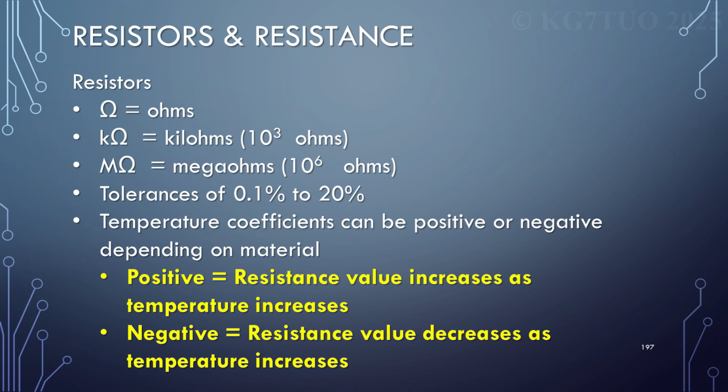As an example of why we should care, the older transceivers that had tubes and discrete components, resistors, capacitors, as they warmed up, they would drift in frequency. So you'd be tuned into your net frequency, and pretty soon you were off frequency because it would be warming up. So you would turn the radio on and then go have lunch and come back, and then it's probably pretty stable. You'd take it up to 15 to 20 minutes, and it would start to stabilize. But you just know that in that first 15 or 20 minutes, it would drift.